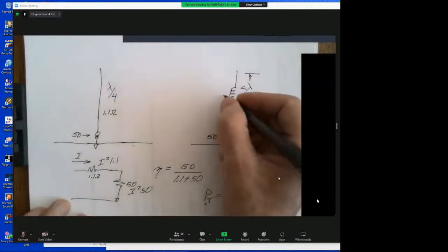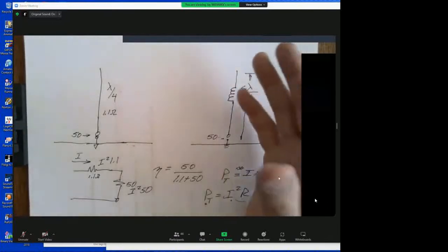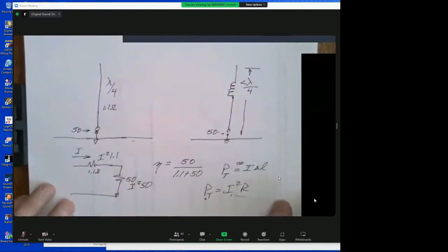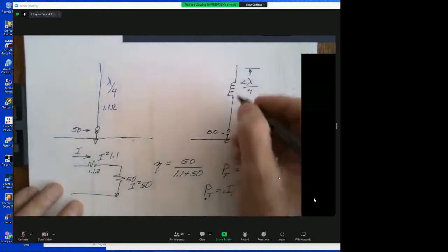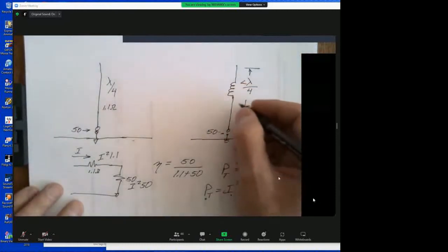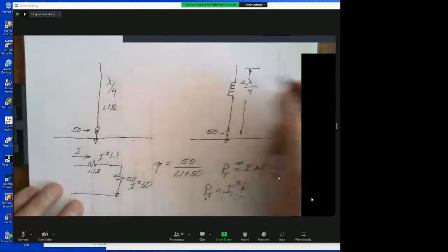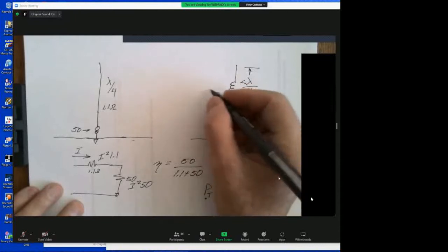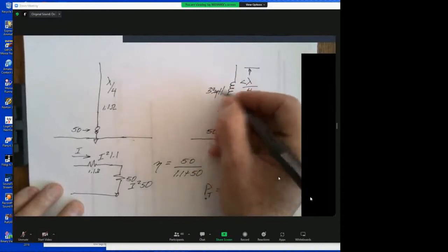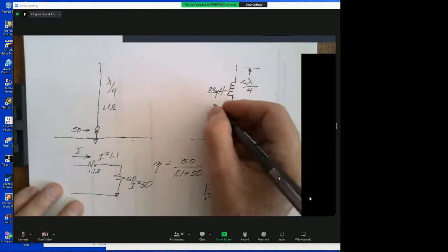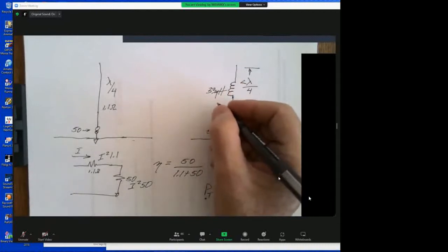Well, it turns out you've got a certain amount in this coil. Coils have losses, and that has to do with the construction, the wire, everything that's going on with them. And you may end up, for example, in this case, you have a very short antenna, only 8 foot or about 2.5 meters. You have a coil here, you need 33 microhenries. It turns out this has a resistance of, I'm looking for it, I figured this all out beforehand.